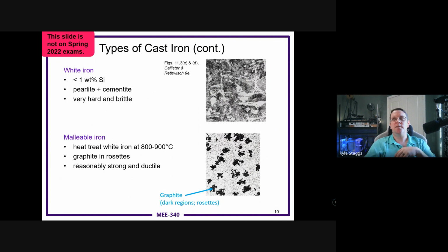So in this case, based on looking at the grain structures, there really is not going to be a lot of easy movement along grain boundaries. These are not usual shapes. They're not rounded at all. And so those grains are not going to want to slip and slide past each other. So again, very hard, very brittle. It'll just tend to fracture along very jagged lines, which is what you see in the actual material.